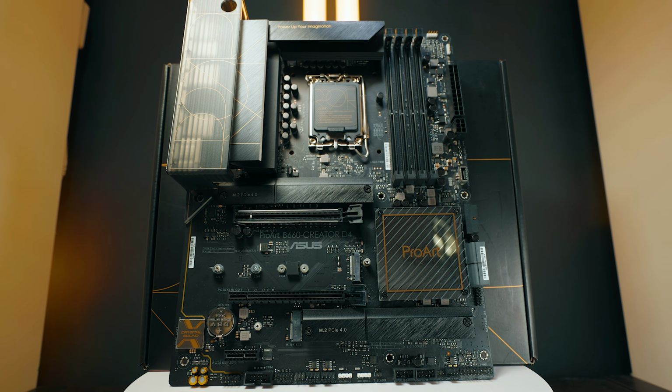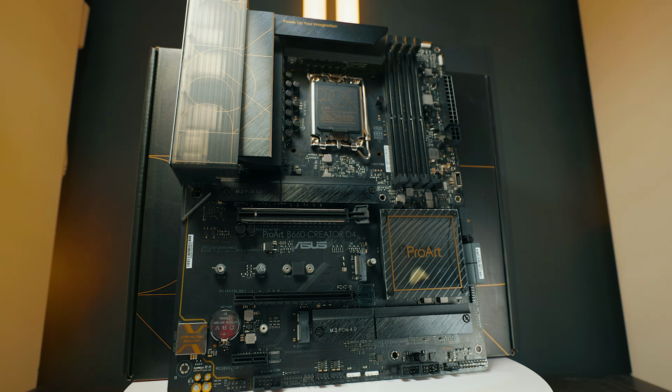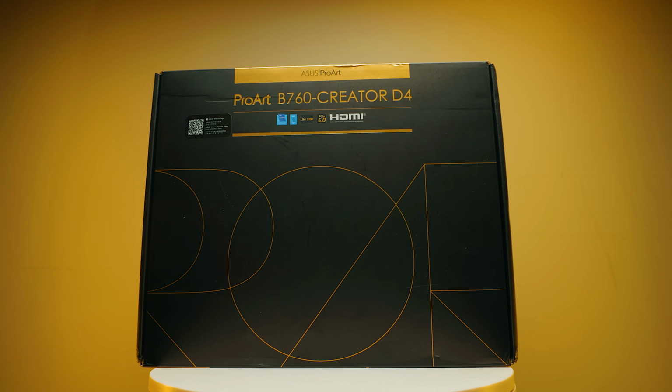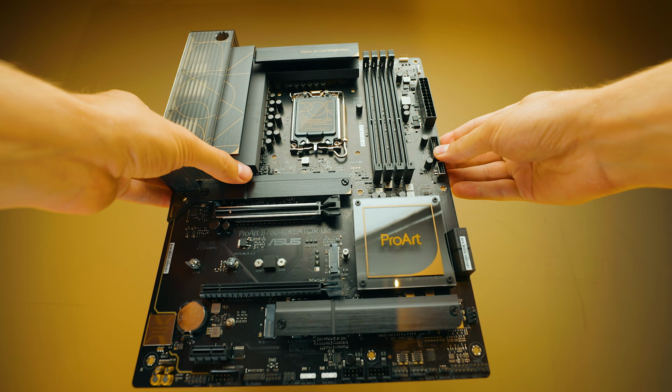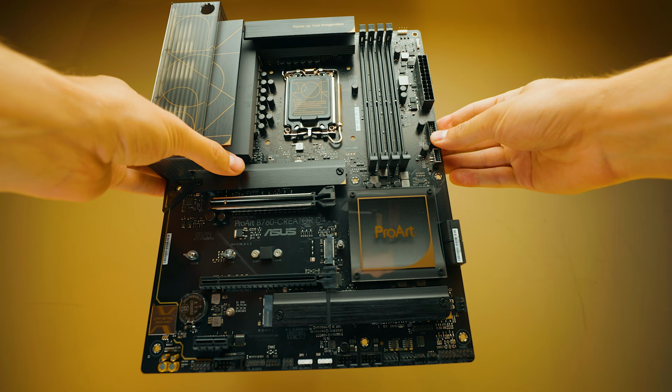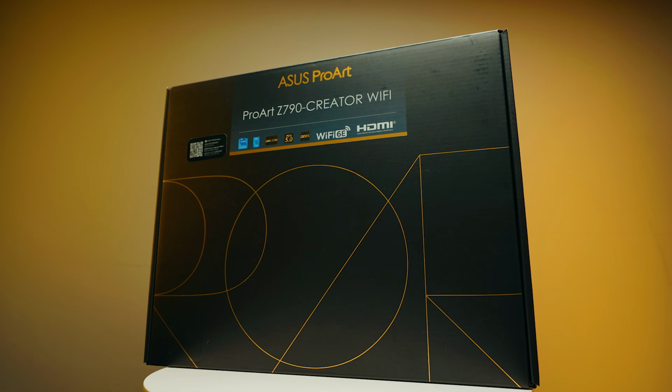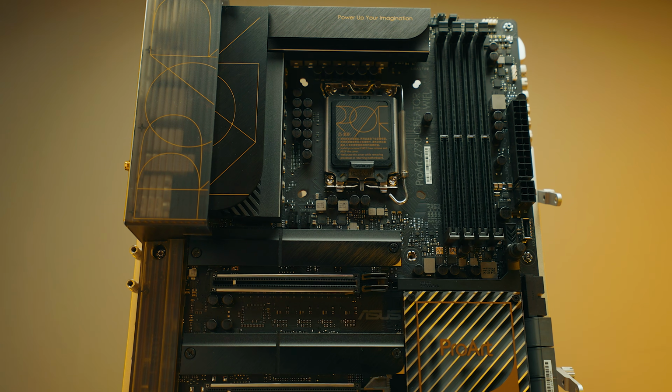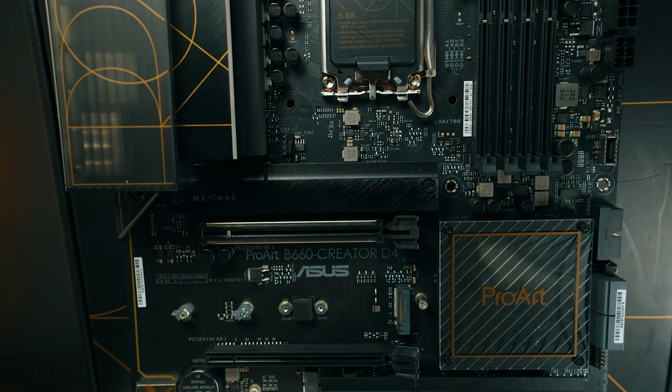And thirdly, the motherboard. If you have some of the lower end motherboards, the way that the signal travels in there is not going to be as optimized as some of the higher end motherboards, and the higher end motherboards often, because of that, will support higher RAM speed, because the signal integrity is going to be less noisy. Think of it as there's less noise and other bits coming from there, so they can actually keep the faster RAM speed. So having a Z790 motherboard is a little bit better than having a B660 motherboard, for example. But that's not always necessarily the case. But if you just want to get the fastest RAM speeds, having a higher end motherboard does factor a little bit into the equation.